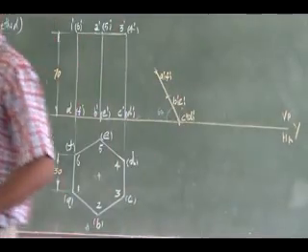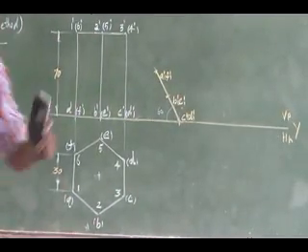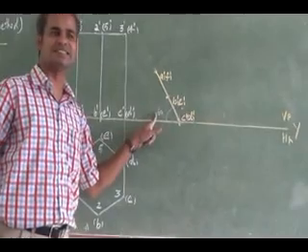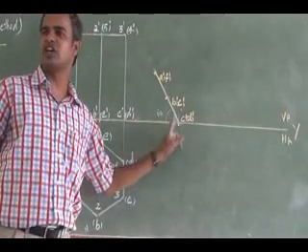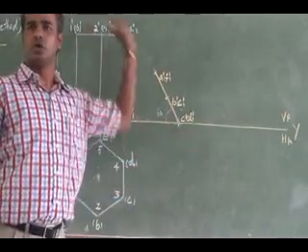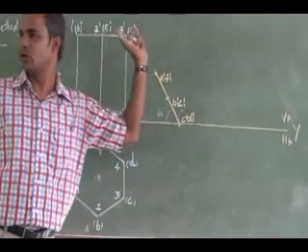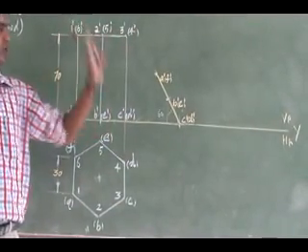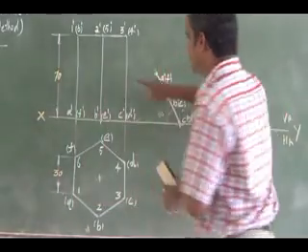So this is what you have to do. The axis inclination will be given, and you convert it to base inclination, that is 60 degree. Mark the resting edge or resting corner on the reference line. You redraw the base to that 60 degree inclination. Now I can redraw this.